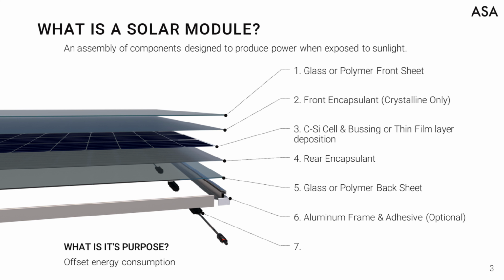Traditionally, an aluminum frame wraps the edge of the solar module to protect it during the installation process, add additional moisture protection, as well as providing a standardized means for mounting. That frame can also be adhered to the back of the module or not be present at all, should the mounting means accommodate frameless glass. The junction box is typically adhered to the rear side of the module, or in the case of some frameless modules, on its edge. The junction box features a positive and negative connection that enables stringing multiple modules together in series.